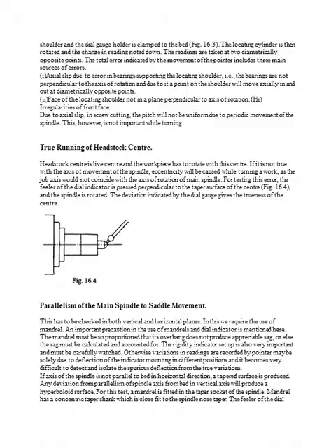Next is the true running of the headstock center. You can see the headstock, then the spindle, then the live center, which is a rotating part of the headstock. True running is the rotation of the headstock about its center, to check whether it is about its axis center or not. The headstock center is the live center. When the workpiece is held in the headstock, it should rotate with the headstock center. If not, eccentricity will be generated on the workpiece.